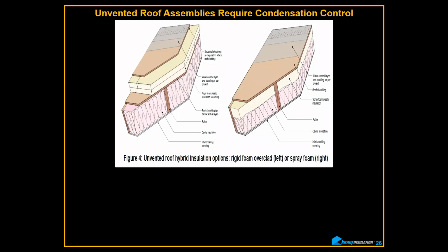Yeah, so again, just repeat the same 2 options. Obviously, you can do this with a fibrous material. You have to make sure that these are airtight assemblies. That's the key. You don't want any interior warm conditioned air getting into this assembly. Okay, this would be your air barrier against your roof deck. Here, it would also be added to your insulation. So if you needed an R49 here, let's say you put an R10 here, you only need an R38, basically, down in here.